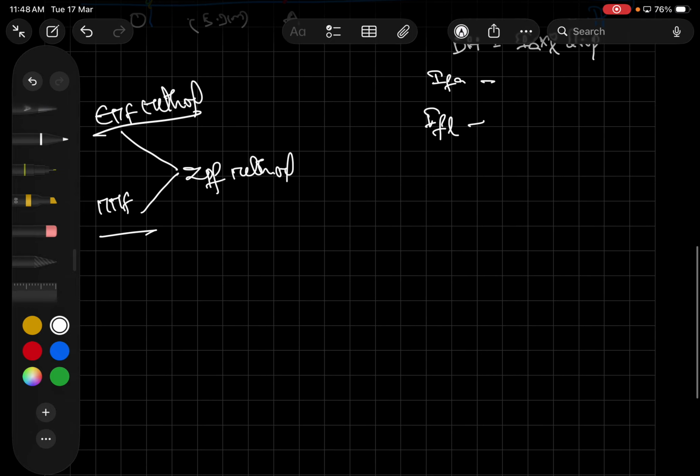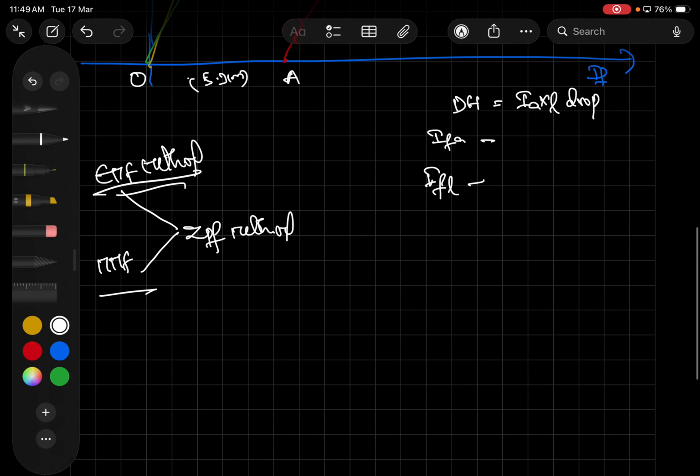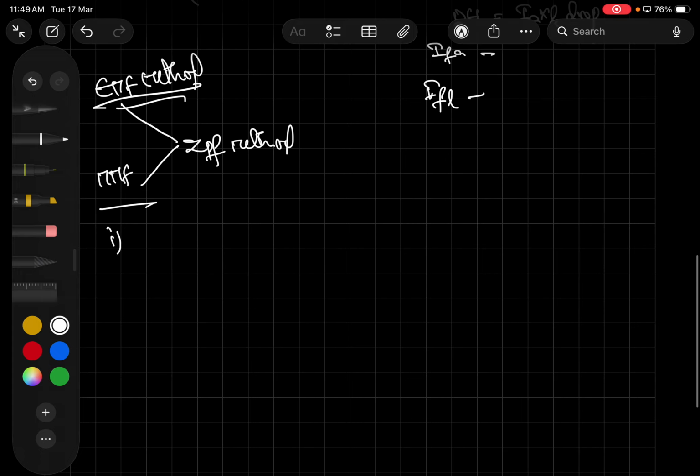So what I am doing here, first I will implement the EMF method in this method. Whatever the voltage formula is there for the EMF method, the same concept I am implementing here. By using the EMF method concept here, let's assume ER. It's not the final voltage. Normally we assume directly E naught equal to the generator voltage or no load output voltage. Here I am considering it as the intermediate no load voltage.